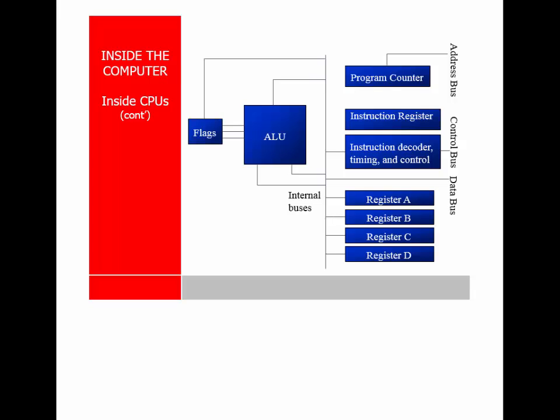Flags are exactly that. The processor raises a flag when something happens. We subtract two numbers, the result is negative, we've got a flag. We add two numbers, we had an overflow, that sets a flag. So we've got various flags that we set. We do a comparison between two numbers, and if they're equal, it sets a flag. So if we can look at those flags, we can do things with them.